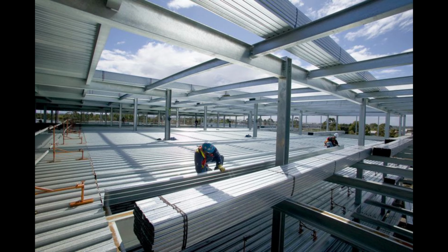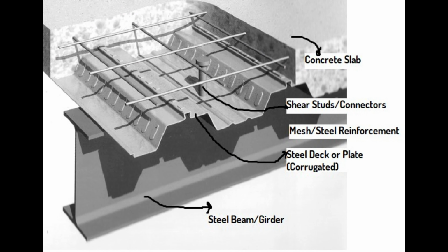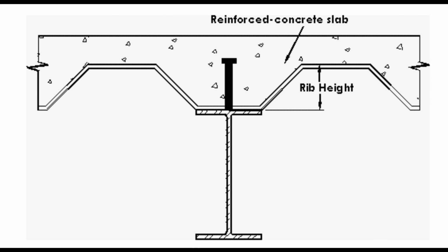The simple assessment for steel floors. The following design procedure is based on a parametric study of a wide variety of regular floor grids modeled using an approach and is suitable for composite floors. The design procedure for assessing the dynamic performance of floors comprises definition of natural frequency, definition of modal mass for the floors, evaluation of the response, and acceptance criteria.